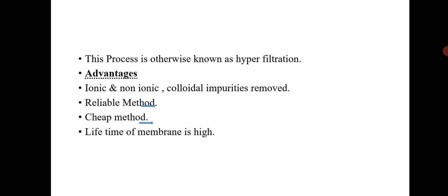It is also known as hyperfiltration. This method is also used to remove impurities like ionic, non-ionic as well as colloidal. It is a reliable method, it is a cheap method, and the lifetime of the membrane is high. We can easily replace the membrane.